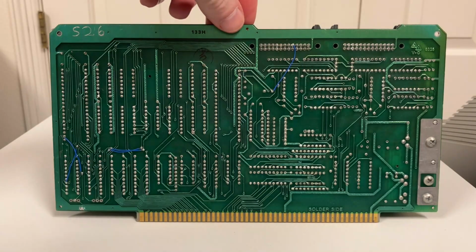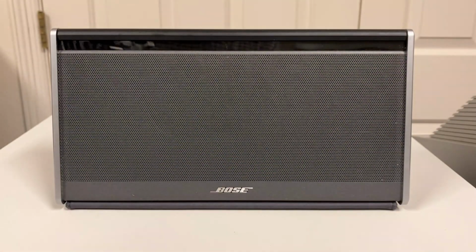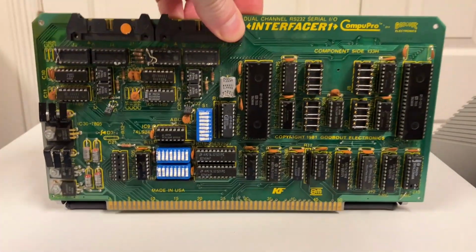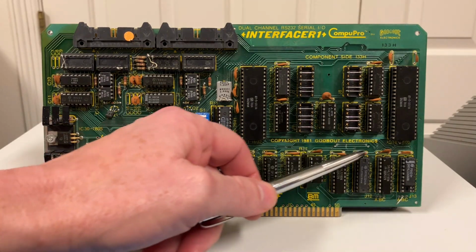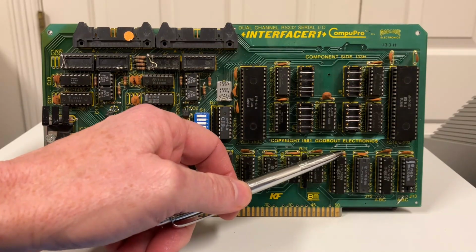All right, now for the console serial port, that looks like a 6850 UART. That has received data on bit 0. The transmit flag is on bit 1. And it's not inverted, it's positive logic. But again, since there's no way to change how those bits are assigned, we're going to have to cut some traces and add some jumpers. So there's 2 parallel traces here that connect those 2 signals.